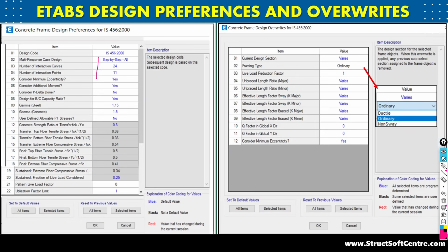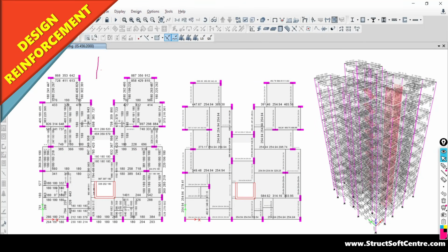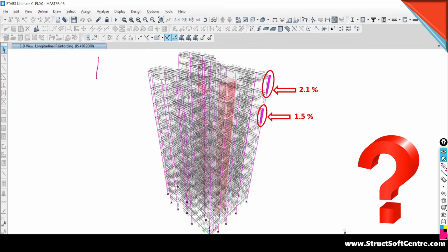Lateral deformation, displacement of the floor slab, beam displacement, all those stability checks we will do definitely. As I told you, after the completion of analysis we will do the detailed analysis result checks, whether all loads were transferred or not, whether your structure is stable or not, everything we are going to cover in detail. So after the completion of the design, you have to interpret whether the design results are correct or not, whether all the design was done as per the codal recommendation or not.